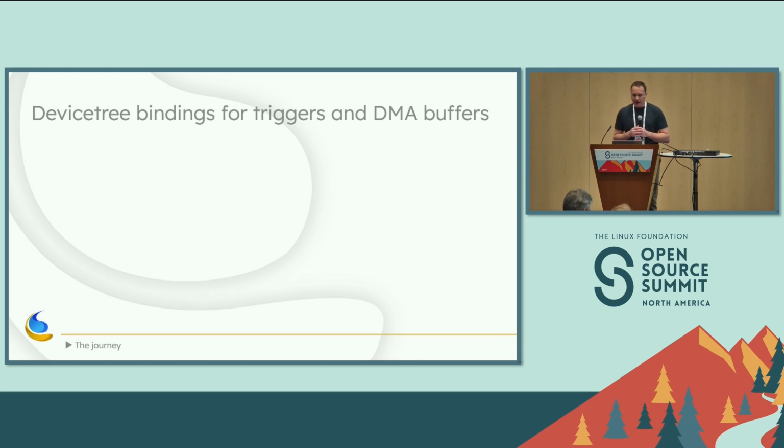So I managed to revive the upstream work that Martin had started and got these SPI optimizations upstreamed, and then moved on to the more specialized hardware offloading bits. And since this is new hardware, of course, we had to deal with the device tree bindings.